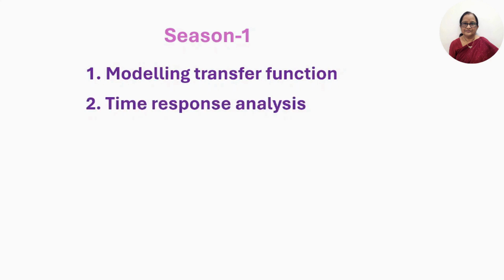The second part is time response analysis for step input and impulse input, and the time response specifications, and how we can find them using the Python control package. The third part is absolute stability: given a system transfer function, whether the system is stable or not.